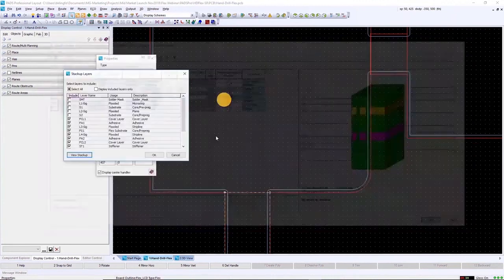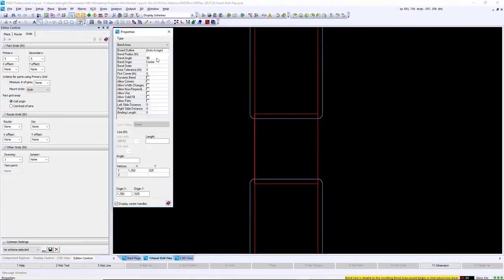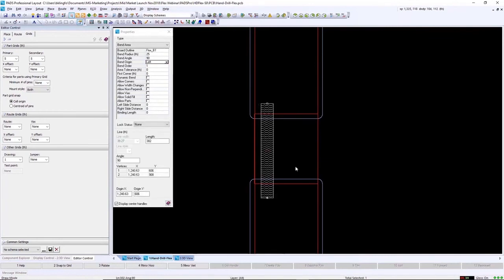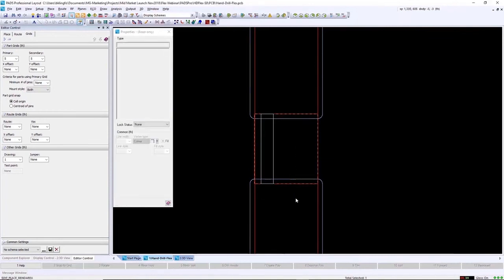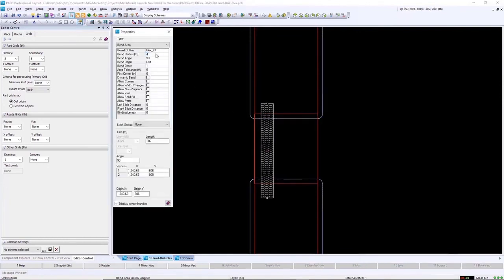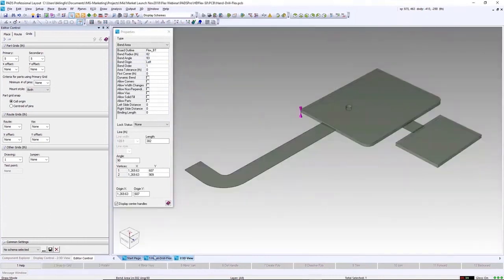The real power behind the flex capability in PADS Professional is the ability to define bend areas, review it in 3D, and use intelligent DRCs for verification. We'd start by defining our basic shape for a bend area, assign that to a bend region. This mitigates any issues with overlapping flex areas. We then set the bend radius for the shape and any of the other various parameters required for this flex region. Let's now take a look at the design with our bend in the flex in 3D.